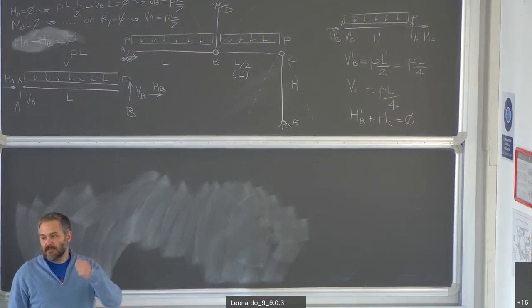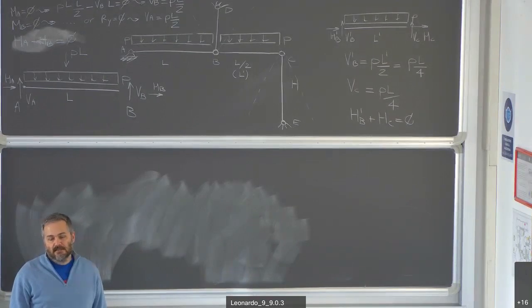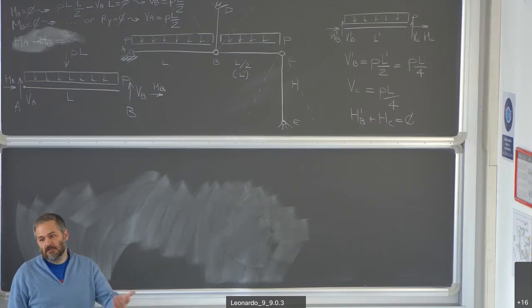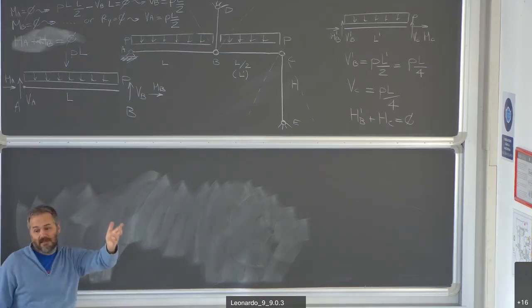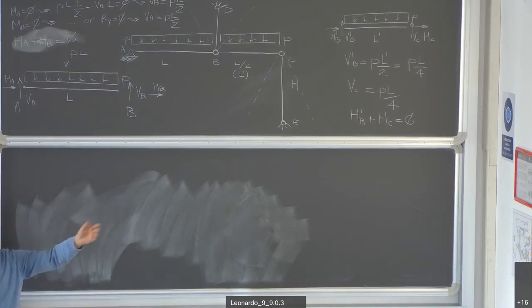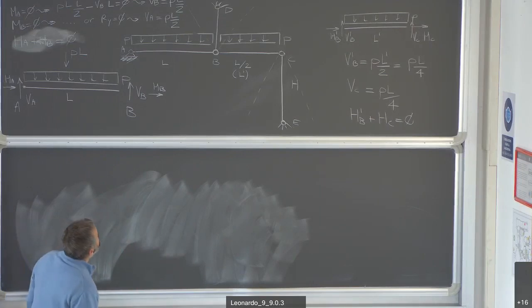That's what I did with the two horizontal members, looking at them, seeing they were straight and constrained to the rest of the structure by means of hinges. I concluded, as regards the shear force, and then we will see the bending moment, they are very much like simply supported. Let's now look at the two vertical members.